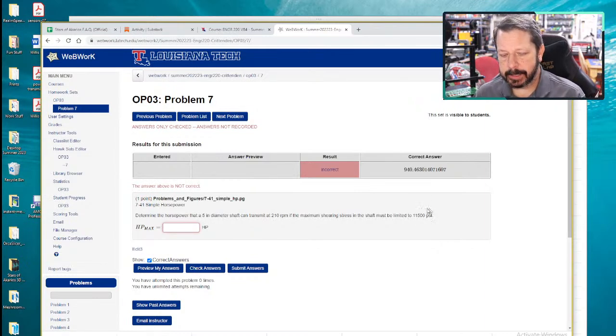Actually, I guess the limit here, why it seems small, is we're limited to a relatively low shear stress. So that's a softer metal, like just a generic steel would be in this range, a little bit higher than this. So we have some factor of safety included, but this is not a super high hardened shaft or anything. All right, so that's that one.